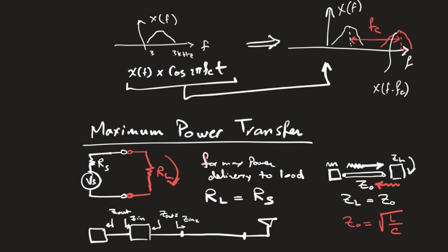So the port that takes the signal in is 50 ohm, the port that takes the signal out is 50 ohm, so you will find 50, 50, 50, 50 connected to 50, you will still see 50. And then the transmission line will have a characteristic impedance, which is 50. And the antenna designer makes sure that the input impedance to the antenna is also 50, right? If not, then you will have a problem.